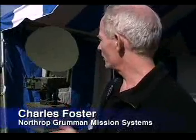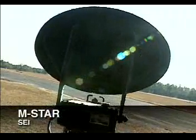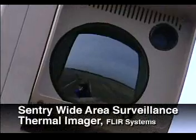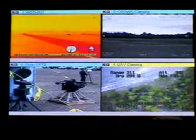What we're pulling in here is a new class of sensors, long-range sensors. This particular device, SEI M-STAR sensor, it has a 42-kilometer range. It will then, through a cue-to-slew capability, relay data to the wide area surveillance thermal imager. We automatically point this imager to the target. We have also integrated a remotely operated weapon system called CROWS that can effectively bring fire to bear on the target once it's acquired. As soon as the ground tracking radar acquires an enemy on the perimeter, it'll send a signal to the CROWS in the direction of the target.